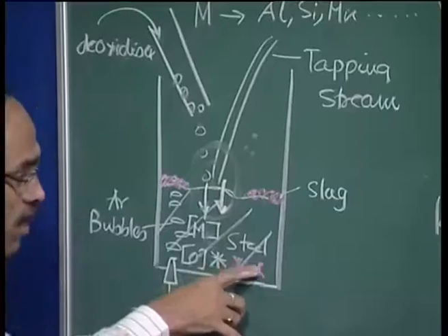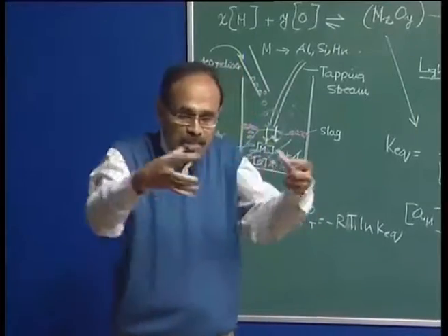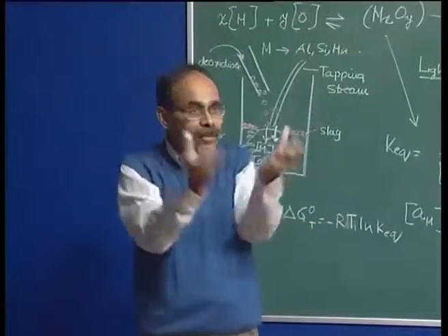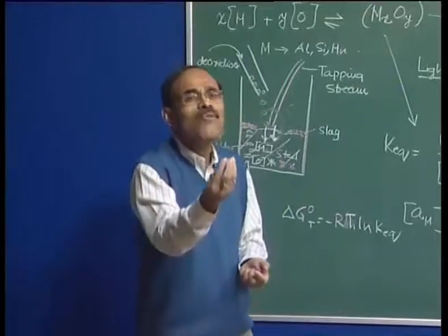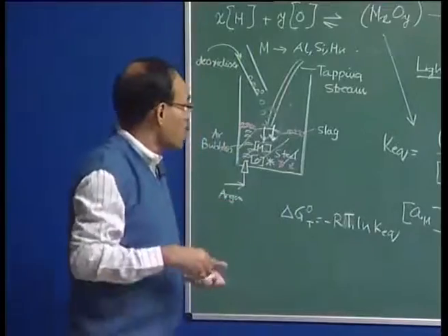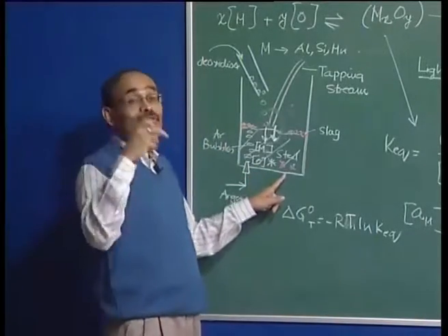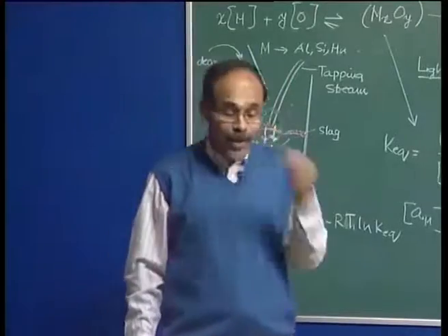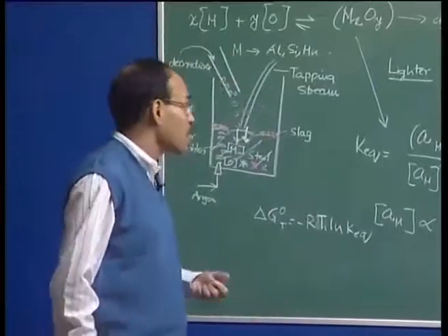On the other hand, if we have liquid deoxidation products, then if they come together, immediately they form a bigger particle. And as you all know, a smaller particle will have a smaller rise velocity, and a bigger particle will have a much higher rise velocity. So, we would like to have bigger particles, and therefore, if we trace back, we would say that a liquid deoxidation product is perhaps more desirable to us than a solid deoxidation product.